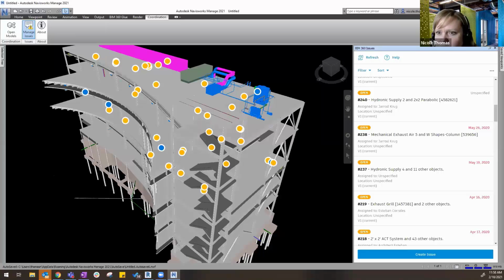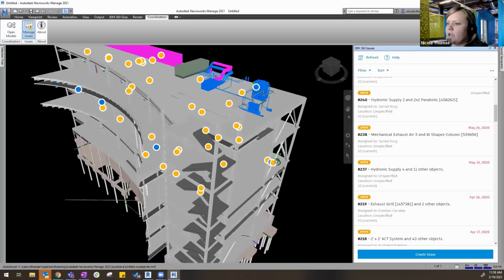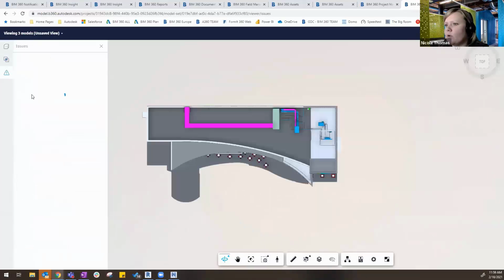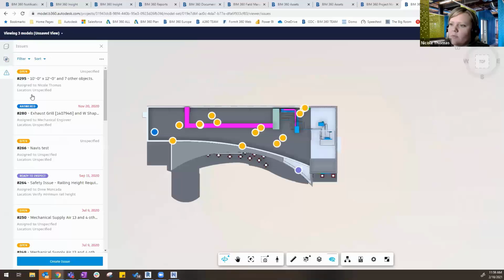As far as a clash report being exported to be used on an iPad, it doesn't come into PlanGrid. There's some future functionality that Autodesk is developing in order to bring PlanGrid and BIM 360 together. So you'll see some new functionality coming out in the next year, so look for that as far as bringing those together. But the issue report is the main export. Any of the issues can be reported. So when I talked about running reports, you can export a report of just all of your clash issues, and that might be a way to export those specific things out.